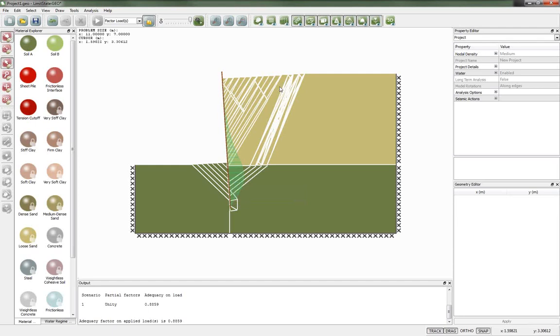And as long as the failure mode encompasses that part of the wall, those are going to be the actual failure collapse state. Normally it'd be best to do these using factor strength mode rather than a factor load mode. But if you have a look at the manual, it explains the details of getting those values out.